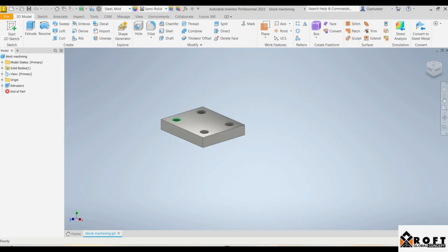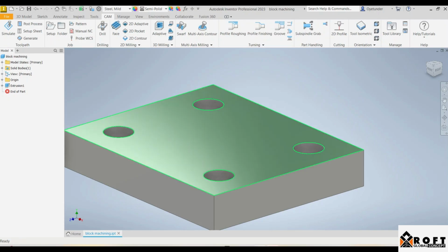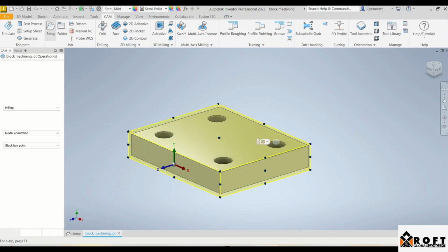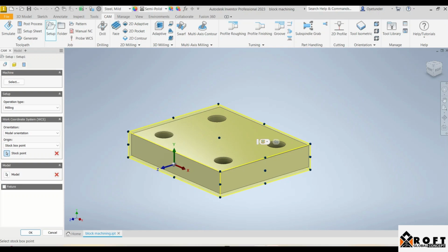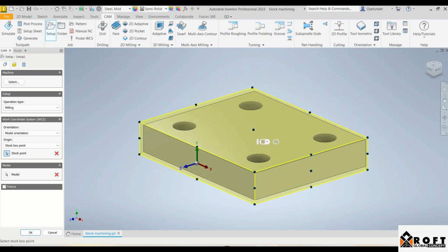Now, if you have Autodesk Inventor installed on your system, if you click on this place, you're going to see the Inventor CAM. The first thing we want to do is to create our setup. When we're creating our setup, we need to define our geometry. CAM always works in such a way that the vertical cut is taken by Z, so look at where our Z is facing. Let's firstly select the type of operation we want to work with. We want to work with milling operation.